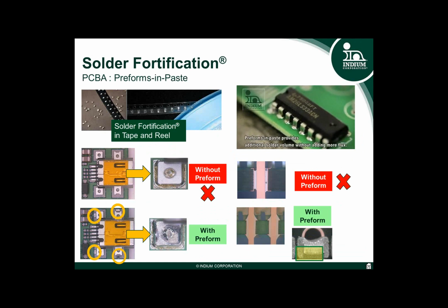Here on the left-hand side, you can see the benefit is that we can have the stencil thickness from the solder paste deposit at a uniform height, so we don't have to consider the rules for step stencils. So we can have the clearances desired. We don't have that factor coming in there, so we don't have unintentional wear on our stencil print process.